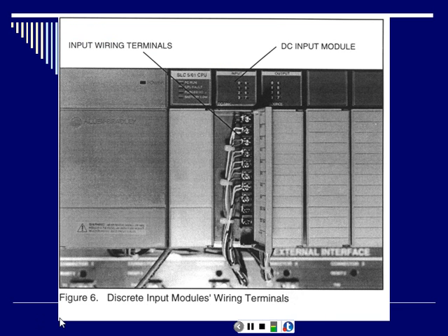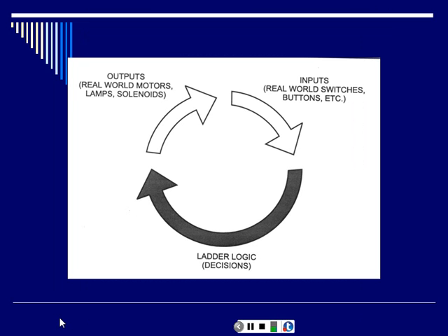This is back to the input wiring. So when you open up these flaps, which is basically the same thing, let's pass that around. If you don't mind, y'all look at it and then pass it back. If you open those up, you actually have those screws, and you can see wires underneath them, and that's all it's showing here. It's just instead of it being on top and bottom of the PLC, these are vertical instead of horizontal. And we'll go look at these in the lab. It's just on a big old huge trainer. I'm not going to try to move it around.